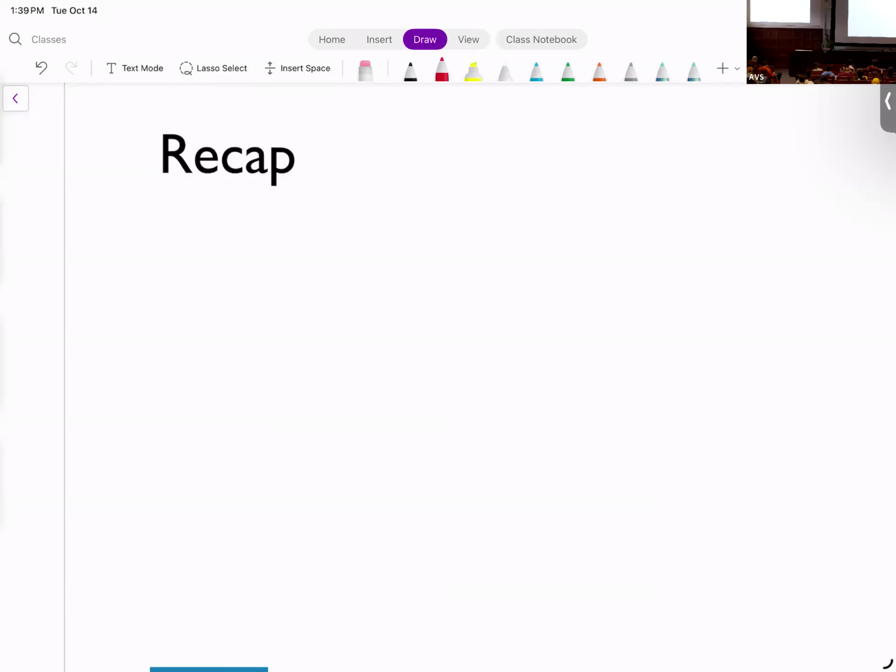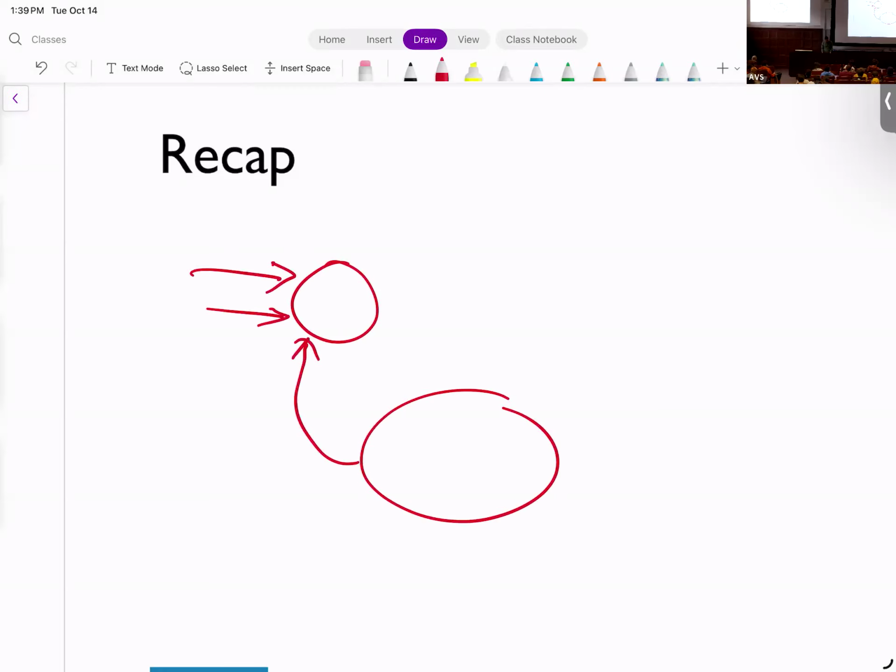Forwarding allows you, for R-type and I-type instructions, since the value is actually generated during the ALU stage and not during the write-back stage, to take the values generated by the ALU and push them back into the source of the ALU. So I basically replace the value that I read from the register file with the values generated by the ALU itself. How did I do that? I had the forwarding unit and I inserted the multiplexer that basically says, okay, discard this, use this, right?